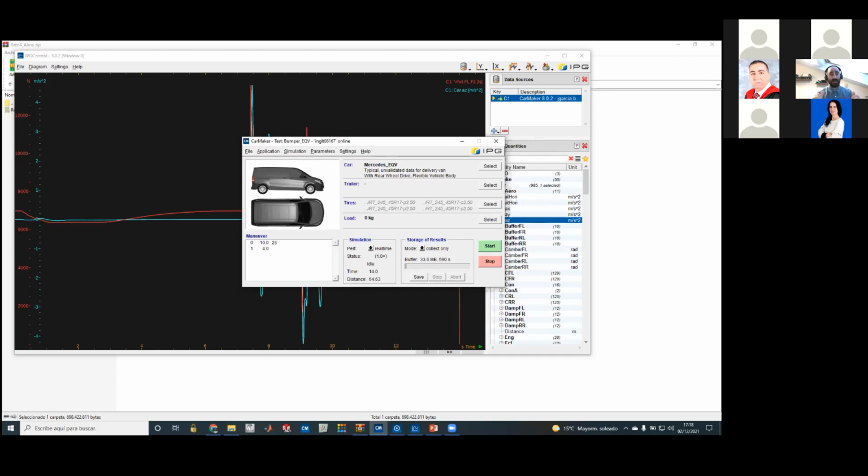The mass of the vehicle is extremely different if I drive it myself or if I drive with my whole family, with the whole luggage, and with the tank full of gas. So here, the natural frequencies of the vehicle, the comfort of the vehicle and the way it behaves in a turn, the understeer or oversteer behavior, will be dramatically affected by that change in the mass distribution.